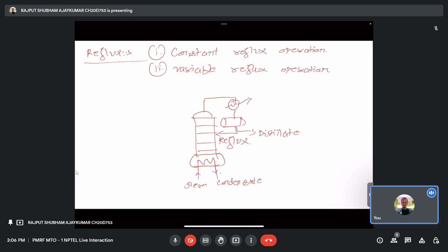In general practice, the constant reflux operation is more common as far as the variable reflux ratio is concerned. In order to use the Rayleigh equation when a column is refluxed, generally one or more iterative calculations are required. Typically, a McCabe-Thiele diagram is used to obtain the information needed in the calculation, which we have already discussed. We also have to know the equations.